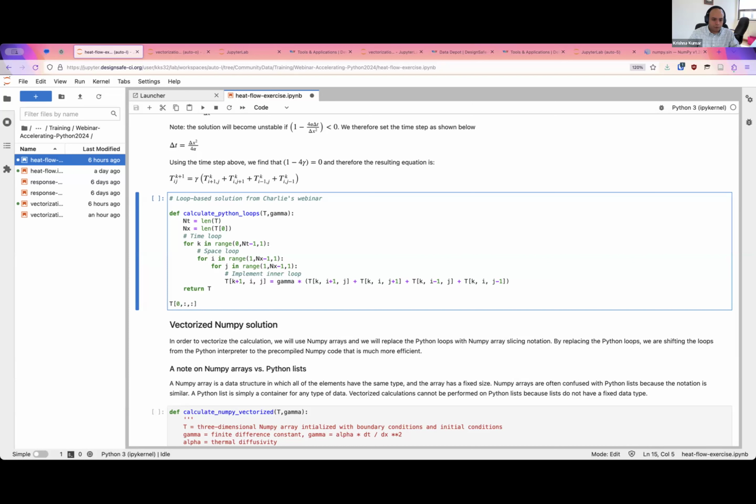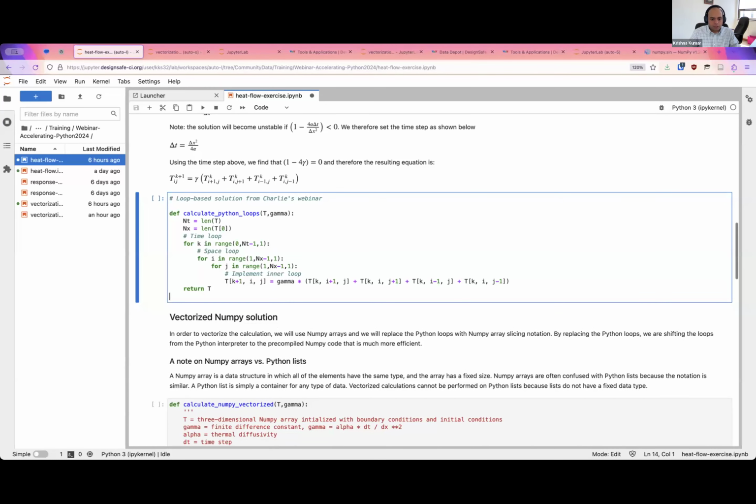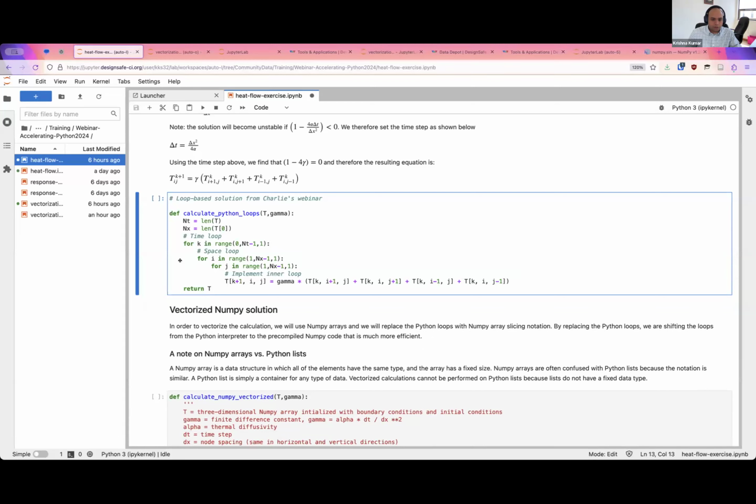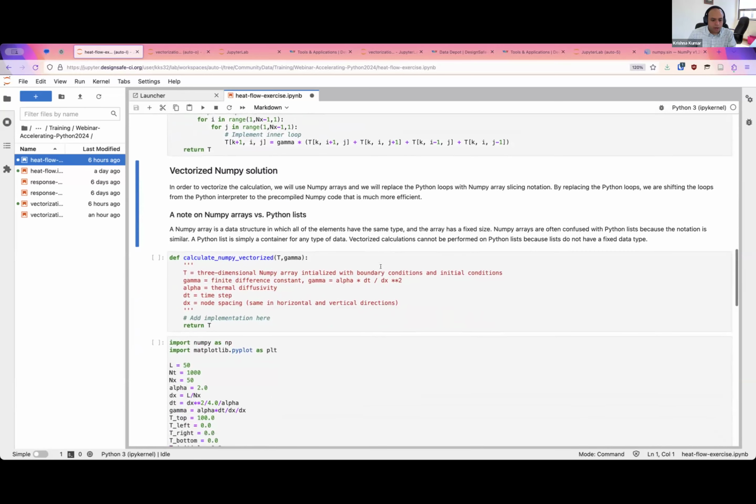All the way up to temperature at time step length of t, right? Which is, in this case, I don't know what t we're going to define, but we can look at the length of t minus 1. This will give us the last time step value. So this allows us to look at what the temperature looks like, but we've done a finite difference implementation. So let's go ahead and initialize that.